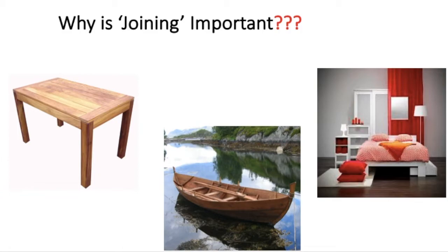You know, a cooking pot, the way it is applied, you need for the material to conduct heat. But then again, you need to hold the pot such that it doesn't burn you. So you will make it with the metal and a polymer or plastic, and then have to join the two because you need those two functions in a cooking pot.